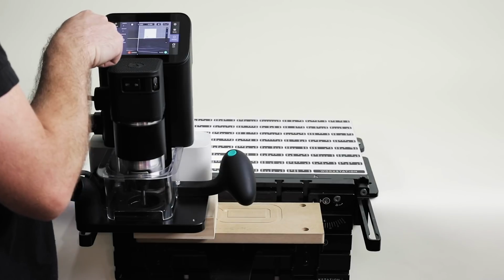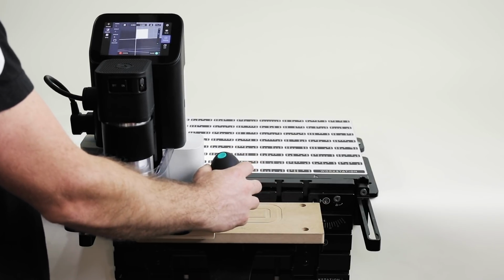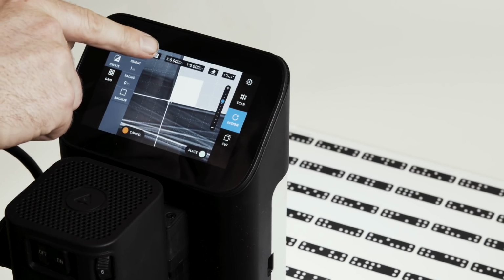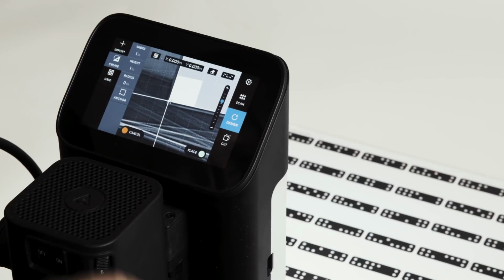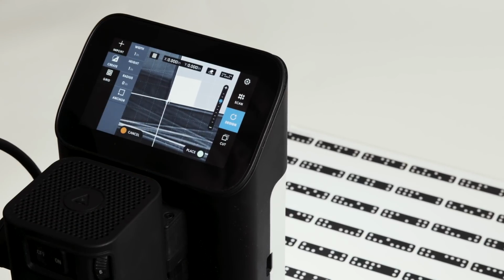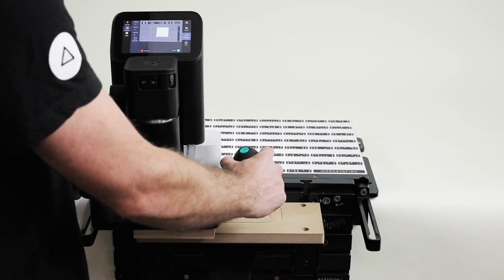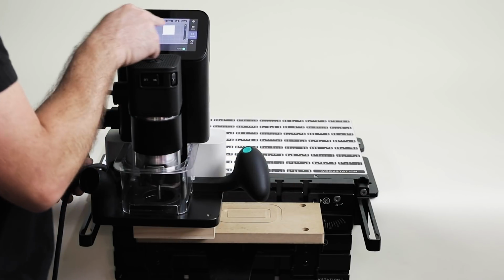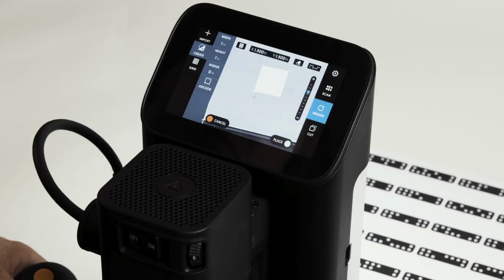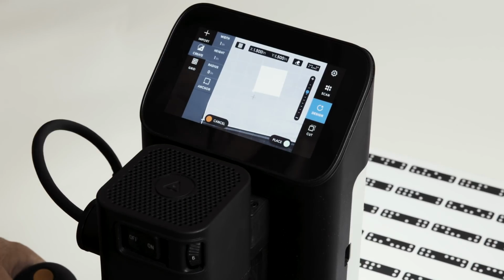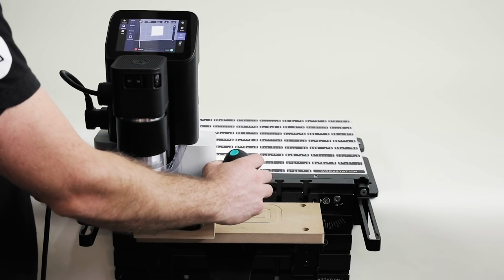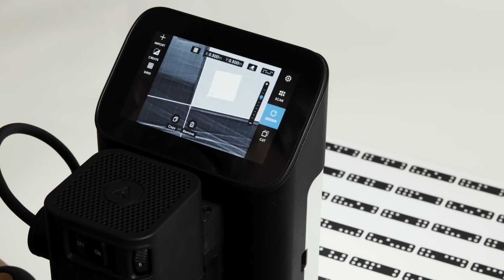Now I'm anchoring to the bottom left corner, which means I can come to this corner and snap it at 0, 0. So I know that that is going to be exactly aligned with that edge. I can also move around, and you'll see my dimensions are updating here. So I'm at 1.5 inches by 1.5 inches, and I can snap a shape there, or come back to 1/2 inch by 1/2 inch, whatever you like.